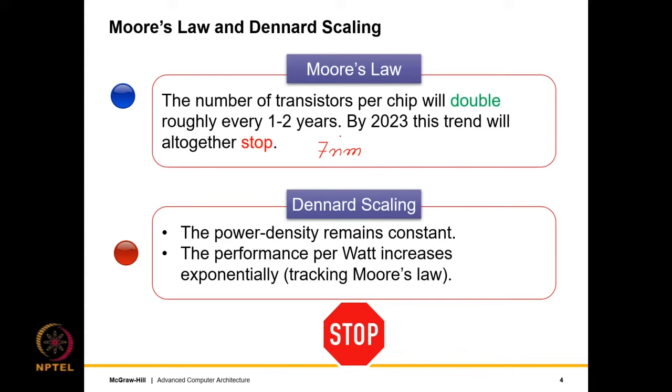about 7 nanometers. All right. So less than that, it's going to be very hard. In a sense, we may go down to 5 or 3, considering the fact that a silicon atom is around, roughly speaking, 0.2 nanometers. This is not more than 35 to 40 atoms. Placing atoms so close by or having such accurate fabrication at the atomic scale is exceedingly difficult. That is why maybe transistors might reduce in size. So the feature size might go down from 7 to 5, or who knows, maybe 3, but that's it.